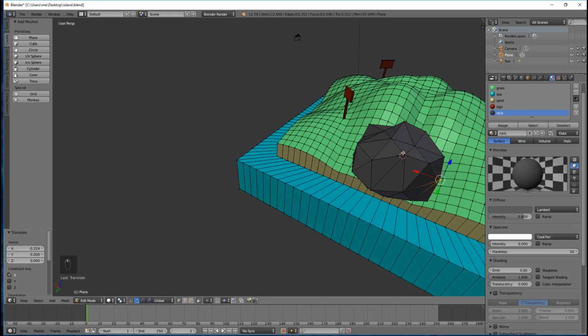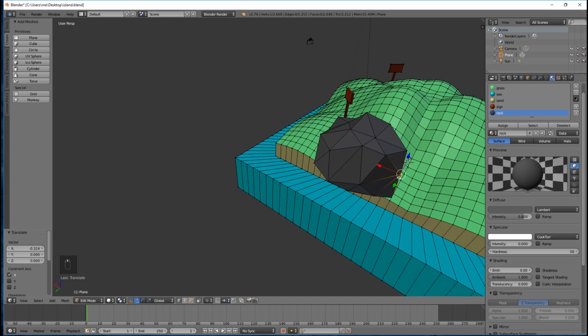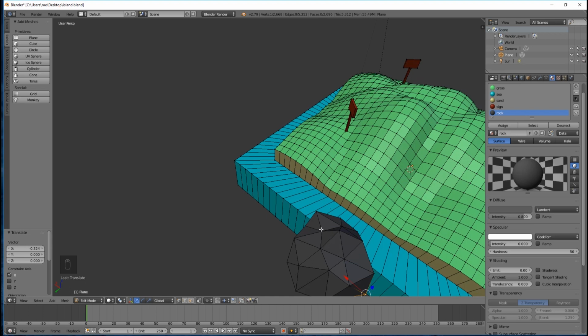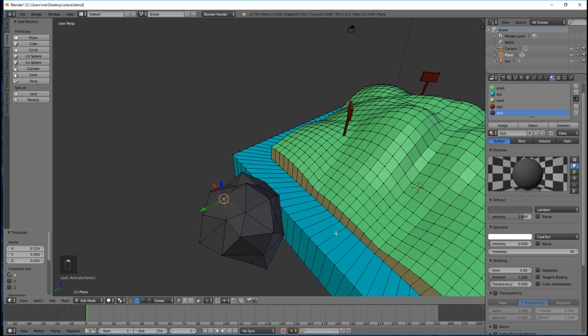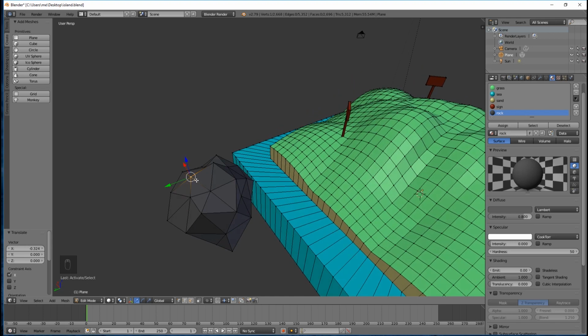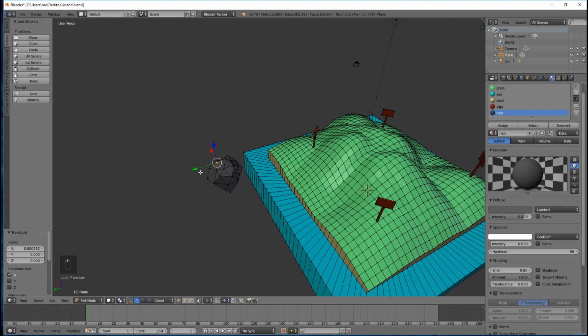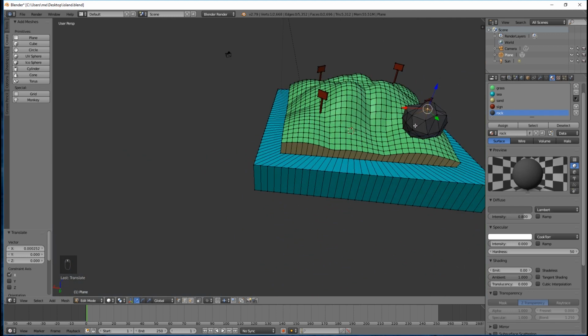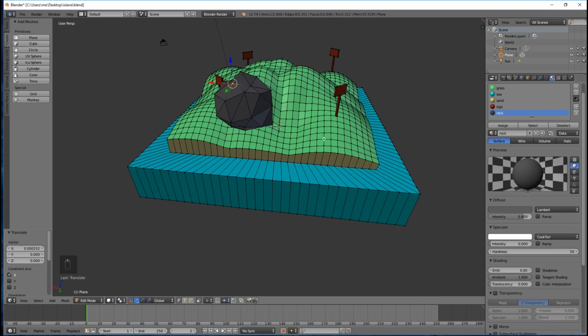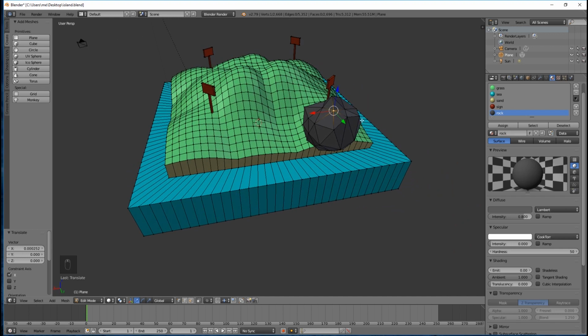So you can use the red arrows or whichever arrow you want here to pull parts of it out. That one here, I think I might pull that point out. I'm going to right click on it and press the red arrow there to pull that out. Not too much, I don't want it too pointy. There we are. I'm going to stop at that point. You can probably see the idea and you can see how it's possible to carry on playing with this quite a lot.